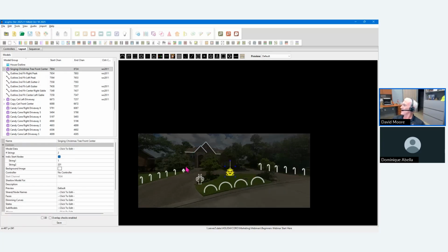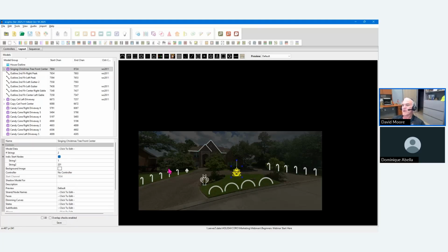So when I look at this, the first thing I'm trying to do is figure out what the major areas and distances are. I can just tell you that we're probably not going to be running a bunch of cables across the driveway. Even if I could put a controller over here on the side and then run the cables across the driveway, that's probably not an ideal way to do it. A data cable with power going across every single one with your car driving over it is just a recipe for disaster. It's just better to put a receiver over there directly in most cases. Now, you may have cracks in the driveway and you run them through the cracks or whatever. Maybe that works for you. But generally speaking, I'm going to isolate that.